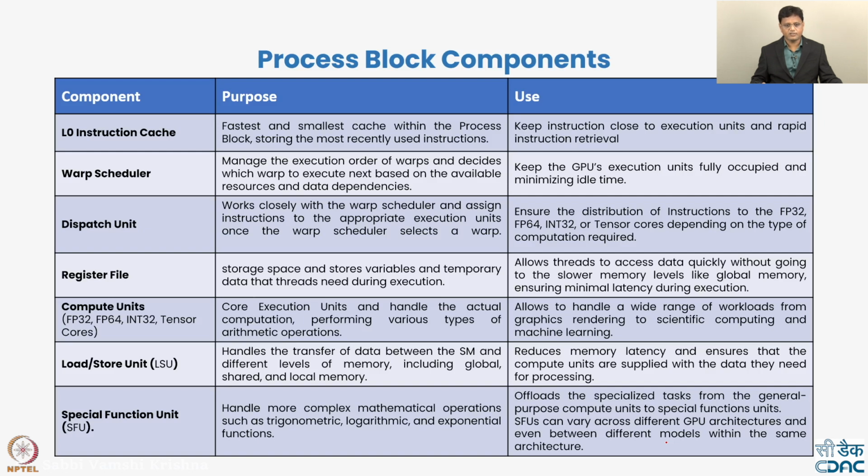Special function unit handles the complex mathematical operations such as trigonometric operations, logarithmic operations, exponential operations, square operations, etc. Whenever such a kind of operation is detected in a program, the dispatch unit sends those instructions, or you can say offloads those specialized tasks, from the general purpose compute units to the specialized function unit.